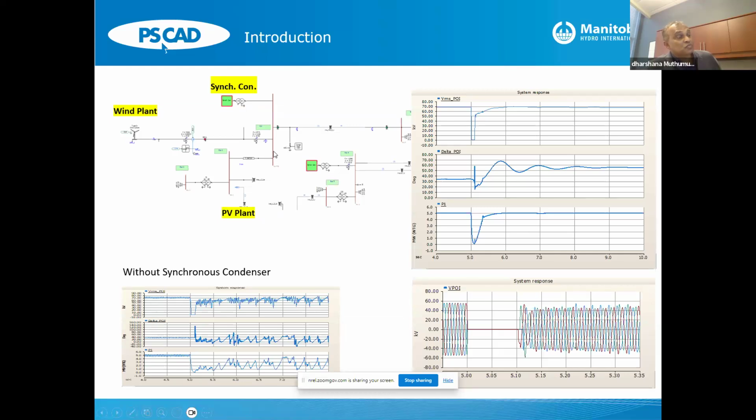the voltage at this bus would change its phase angle because you're changing the topology of the network. You're disconnecting a line, it's a new power flow, the voltage magnitude, but also more importantly, the phase angle could shift.